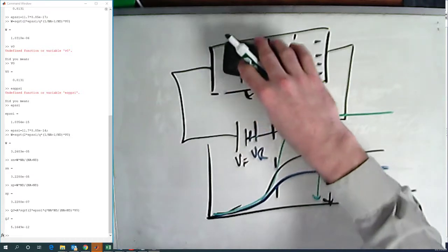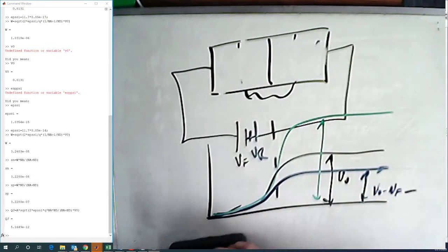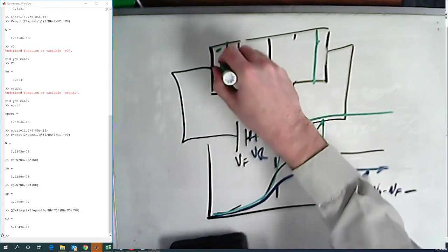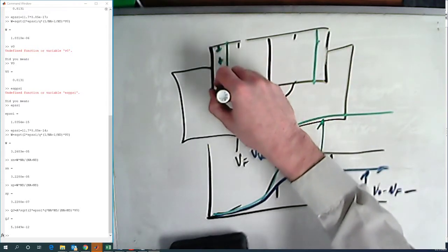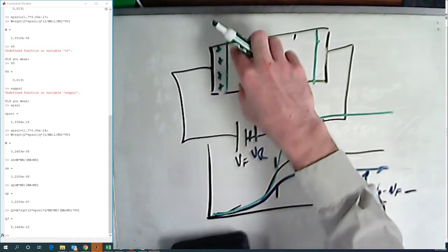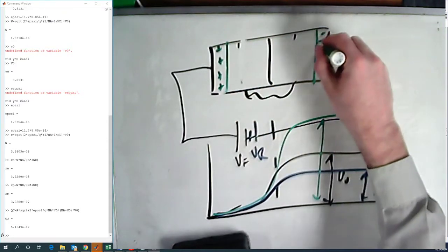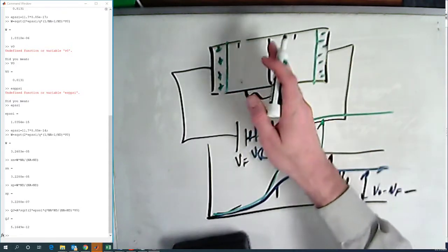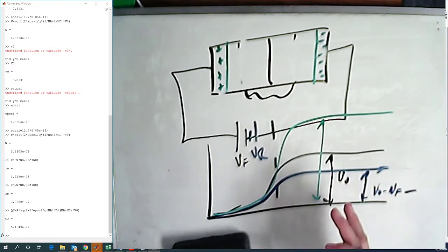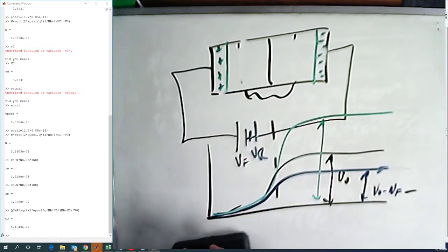Going the opposite way with the reverse bias, our depletion region gets wider. Okay, and so we end up with holes still over here, but we're shoving electrons in here, and they're annihilating each other, and it makes this gap bigger. We're pulling electrons out of here, which makes that region smaller. We're essentially applying a voltage against what exists there, and it just makes this gap bigger and bigger, and no electrons are flowing because it's harder and harder for those to get by from one side to the other.